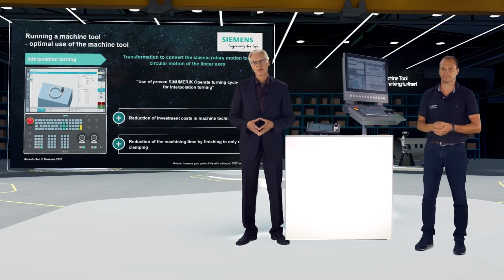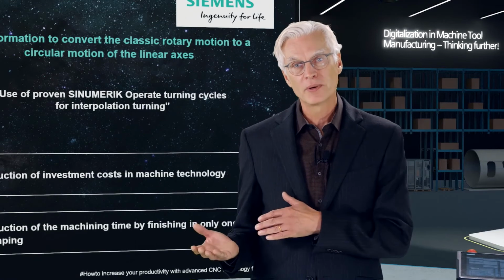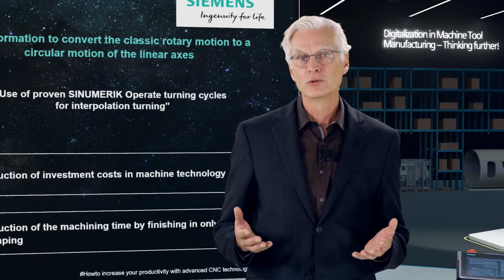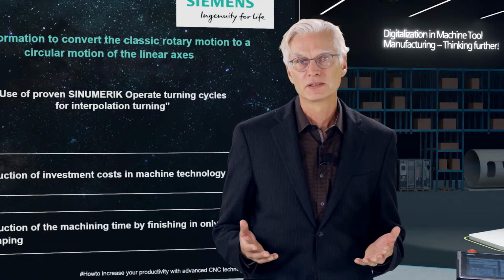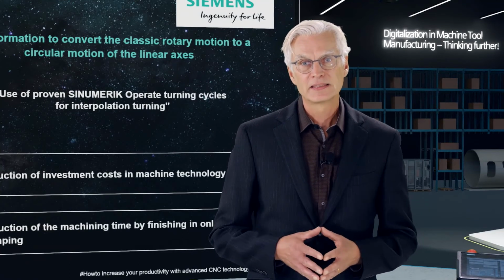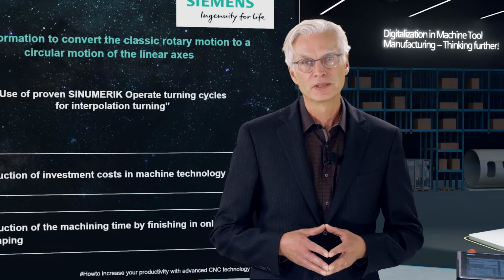Let's move on. In single part production or even in small batch production, we have frequent changeover processes of the workpiece from one machine to the next machine. The user naturally wants to reduce the number of changeover processes. First of all, this costs valuable time, and second, it can reduce the achievable machining accuracy of the workpiece.